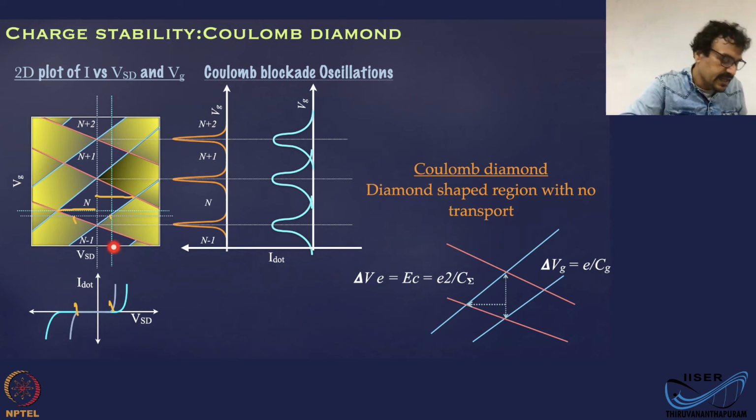So just by taking this diagram, you can get a lot of information about the geometry of the dot. If you have many gates, you can get the capacitance of all those gates by repeating this measurement with various gates. This Coulomb diamond acquisition is a very important and necessary step to verify that you have a quantum dot.